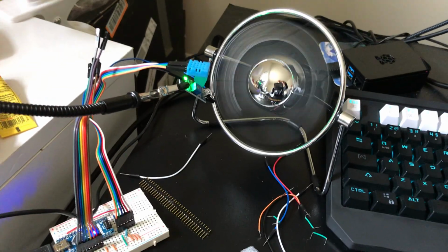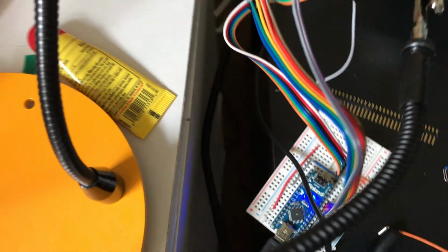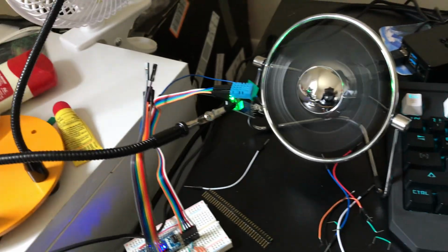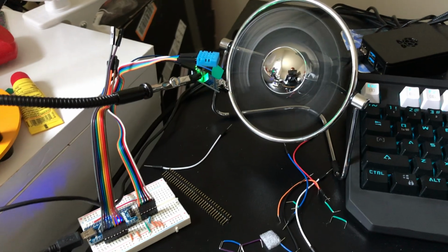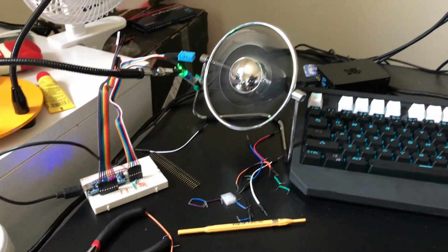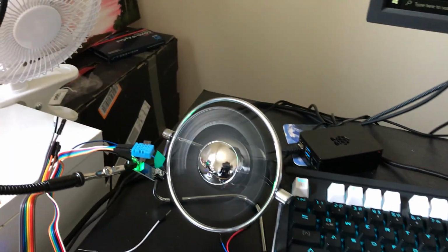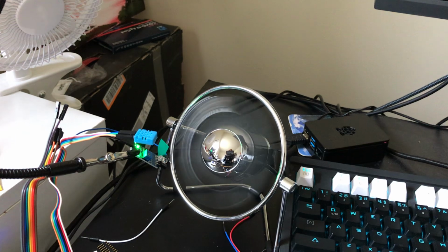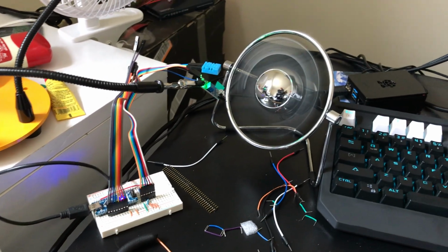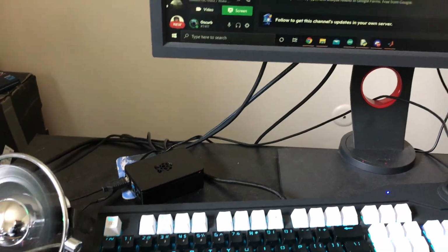We also have our temperature and humidity sensor there connected up to this Arduino Nano that I've got set up. I've also got a bit of a makeshift vibration sensor, since I didn't have an accelerometer on hand to be able to do all that. But here I'll show how this information is getting digested and where it's all getting processed. So it comes from this Arduino Nano, and it gets sent over to my Raspberry Pi over here, and that is all a serial communication.